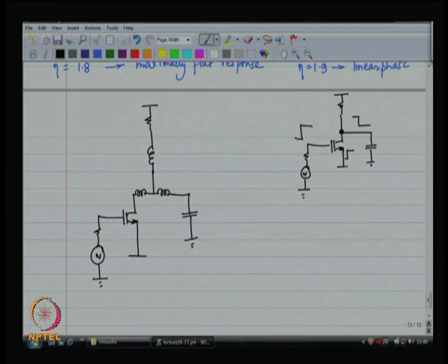Now, because there is a capacitor over there, this is not really going to happen, and even when the current goes through a step response, because the load is an RC, the capacitor is going to charge up slowly. Okay. So, this is what you are going to achieve out of this first cut.